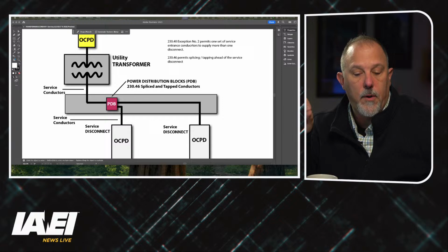when they're service equipment. And also, I would ask whether we've got to think about those conductors from the secondary of the transformer. If I'm looking at those transformer secondary conductors, I have unprotected conductors there as well.